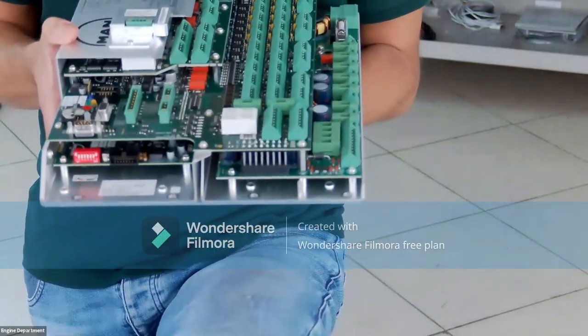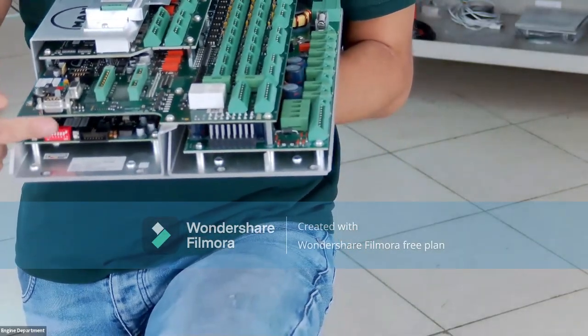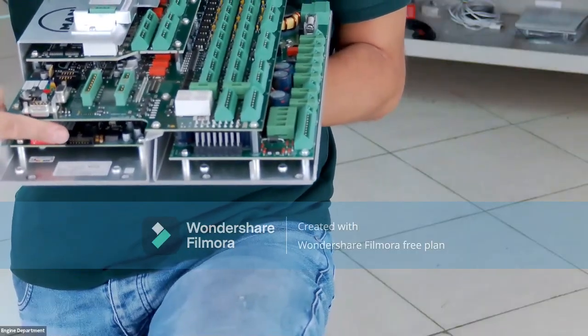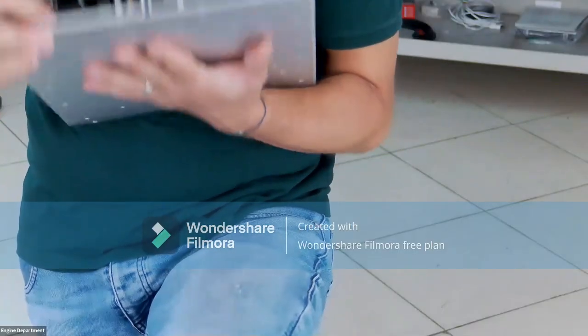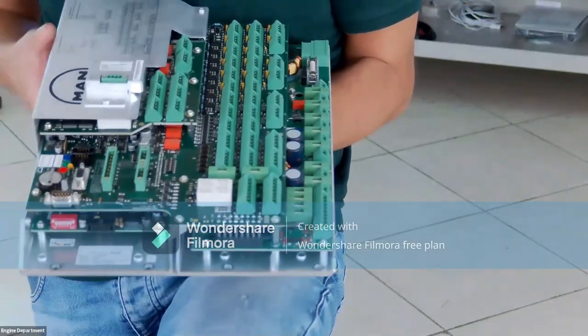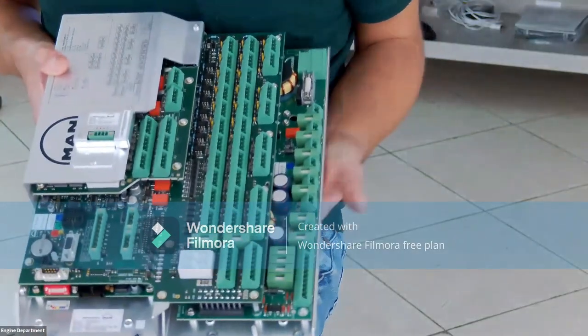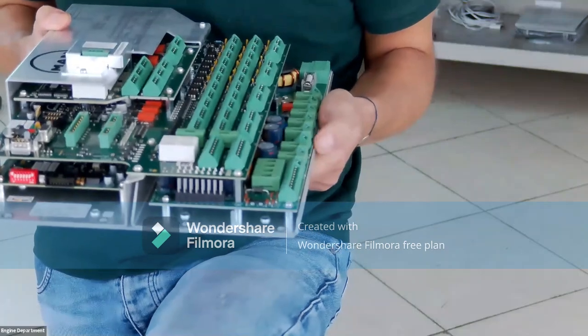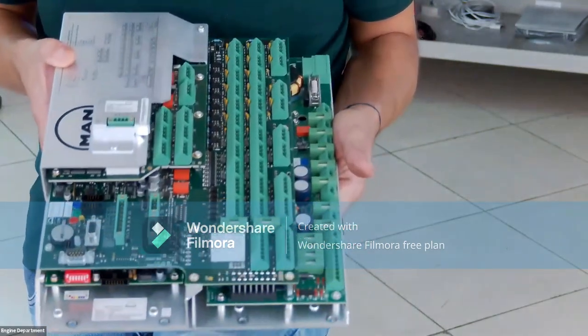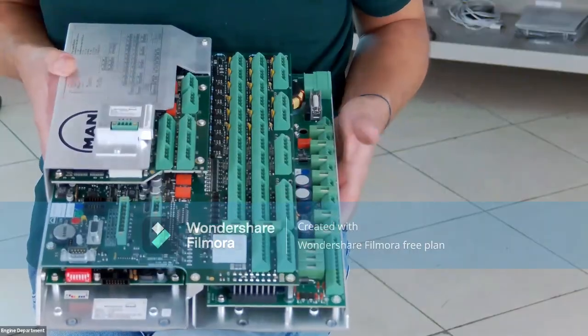Near the DIP switch area, you have a white or a black button which is used to reset. By pushing this button, you reset the MPC. This one from here. Okay, it's a reset button. I make this check: S1 DIP switches, front DIP switches, all of them off, 1 and 8 off, 2 to 7 on.